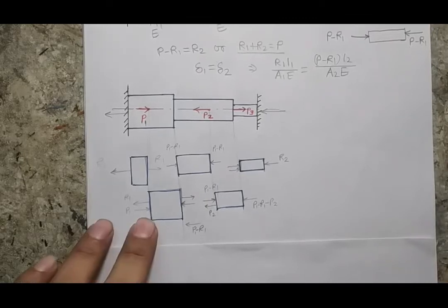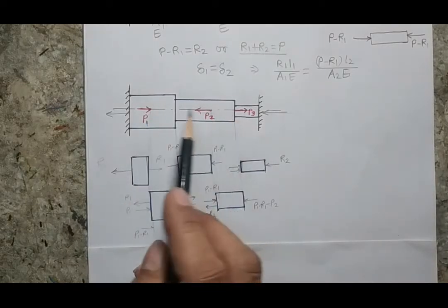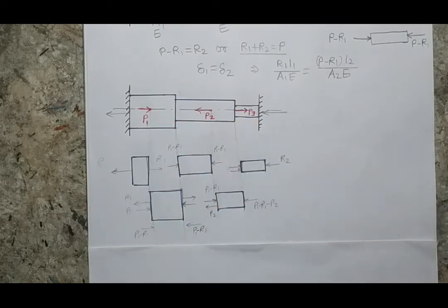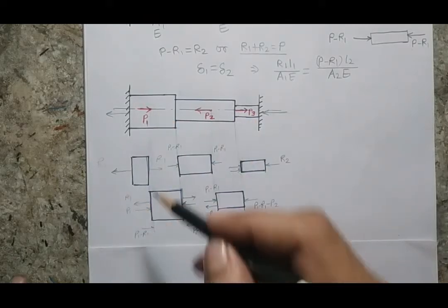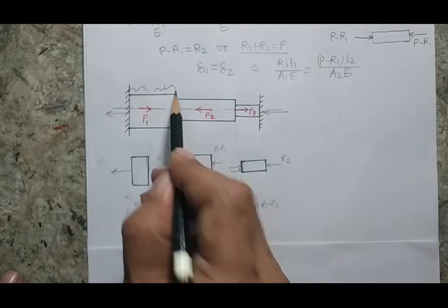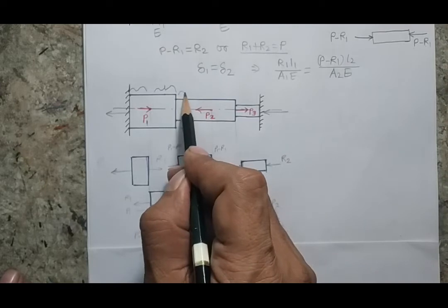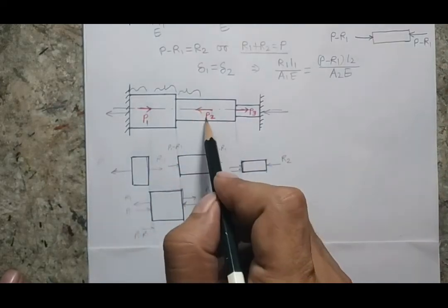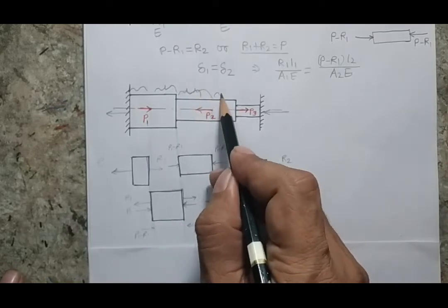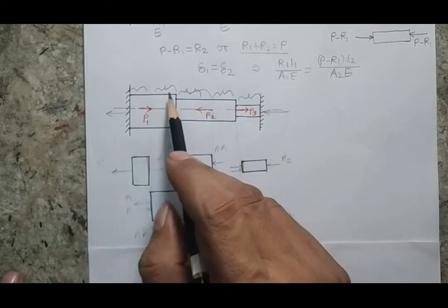I believe that this is a little longer method, so instead of that, what we can do, if we are having forces in this way where the forces are not acting at the junction, but are acting somewhere in between in your body, is consider this part as section 1. Then this is section 2. From here to here, as the cross section is changing, again I can make a next section from here up to here only. Then from here to here I can use another section, and from here to here I can use another section. So in that way I am going to consider 5 sections.